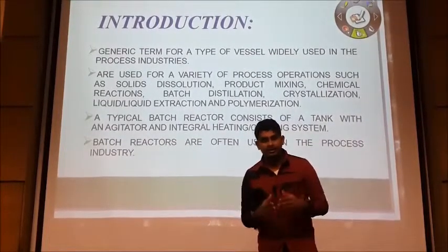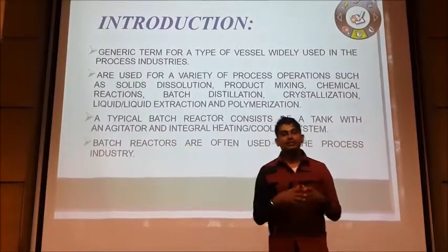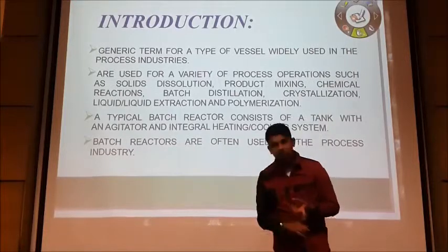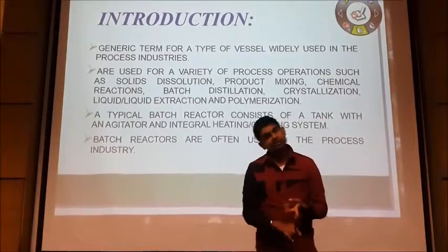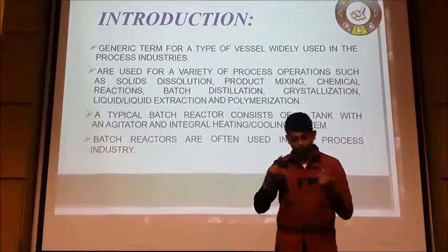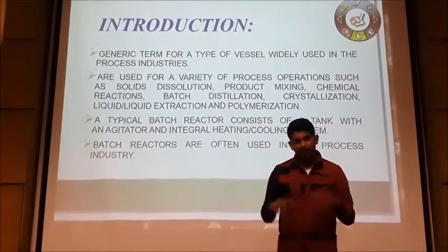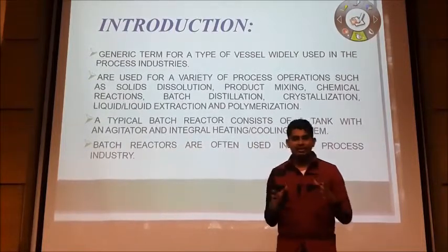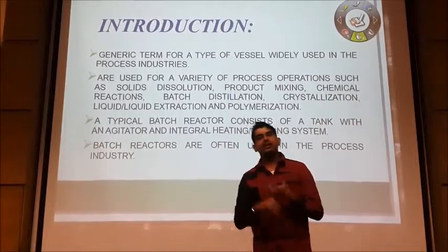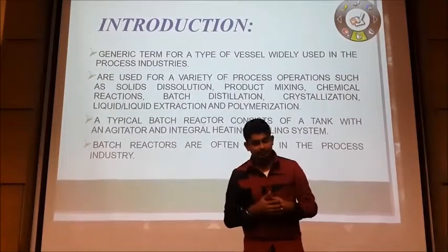Well, batch liquid reactors are commonly used in various operation systems such as solid dissolution, crystallization, batch distillation, and polymerization. A typical batch reactor consists of a tank with an agitator and a heating or cooling system.